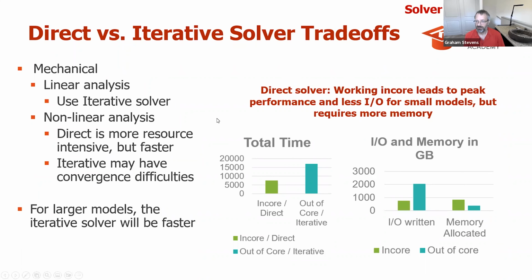And then similarly on the mechanical side, you want to just use the iterative solver for your linear analysis. But when you've got a nonlinear analysis, the direct solver might be more resource intensive, but faster. It might be faster. The iterative solver may have convergence difficulties.